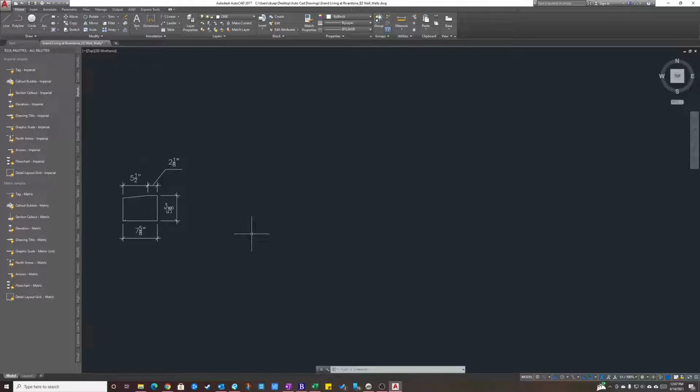So let's go ahead and draw the first window. The W5, W8 window are 7'6" wide. Now, there's several ways to do it. Remember, they overhang by 4 inches. We can either add that to the dimension right away and draw it immediately, or you can stretch it later. It's completely up to you. It just depends on how your drawing style is and how your mind works. But I'm going to show you how to drag it and stretch it.